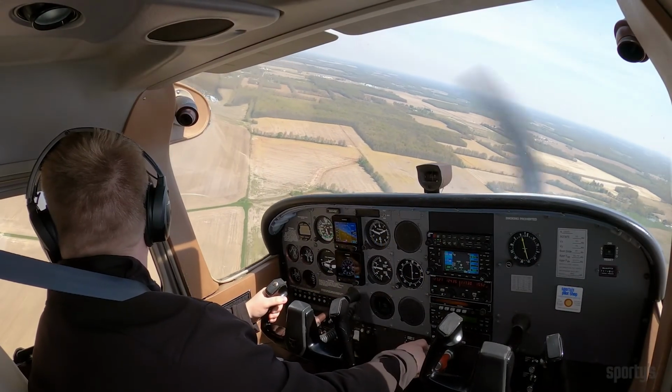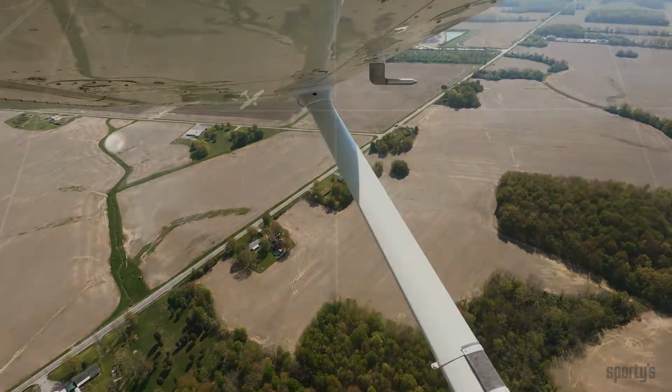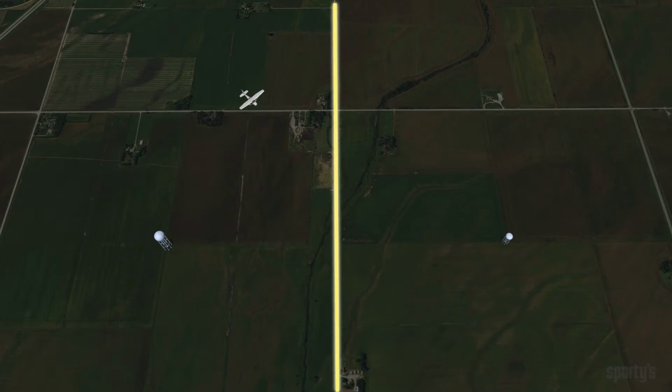Selecting proper pylons on the ground is a key element when performing 8s on pylons. They should be sufficiently prominent so the pilot can view them when completing the turns, while also adequately spaced to provide time for planning the turns. Choosing points on each side of a straight road make excellent pylons and assist with pilot orientation.